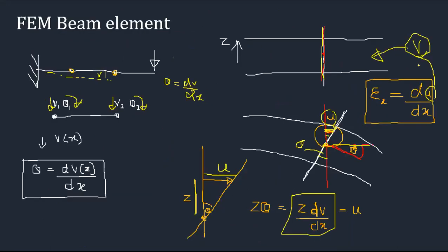If v is a function of all four displacements, then you know that u is a function of v, so u is indirectly a function of these four displacements. So if you take this du over dx or whatever, that will be a function of all four displacements indirectly, right? So if you take the longitudinal strain, you have the relationship with all four displacements. That's why we take longitudinal strain. So that becomes a one-dimensional analysis, right?